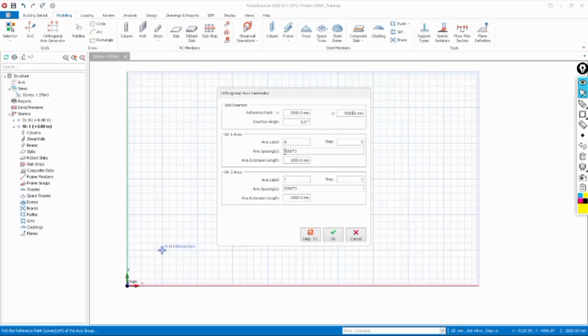So the first is the distance you want, and it is separated from the number of spaces you want by the asterisk symbol. So in this case, let's assume that I want the distance of 4000 millimeters at a number of 5 different places. Okay, so I can just have that just like so.